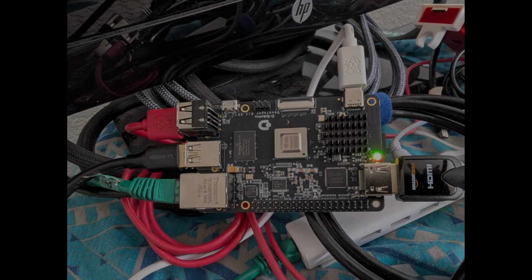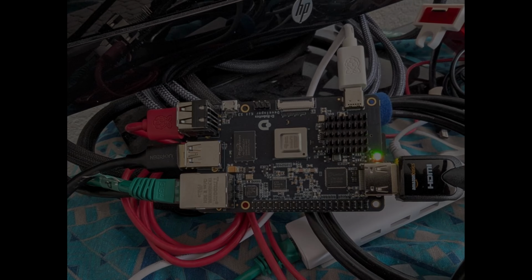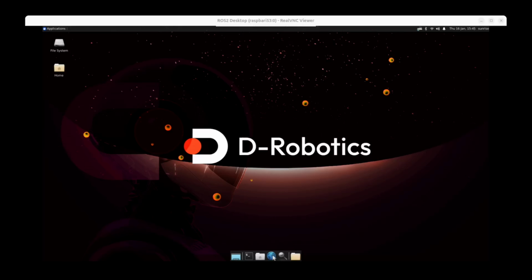Insert the SD card into the bottom of the board in the appropriate slot. Then connect all the peripherals first before connecting the power. Once the power has been connected, the system will start to boot. Check the status lights. Once you get a steady green, then you know that the system has booted up, and the screen should look similar to that shown on the slide. After the system has booted up for the first time, the first step is to establish network connectivity.